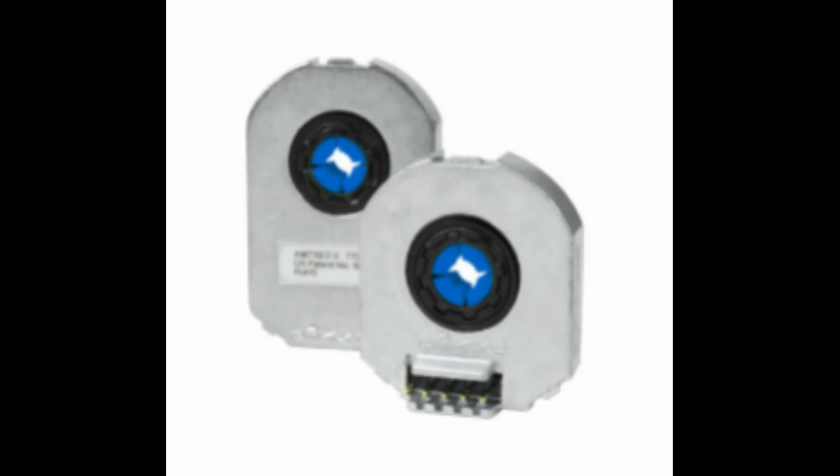Strengths of rotary encoders: highly accurate at measuring rotation, and easy to implement in a system. Weakness: it needs to be homed every time it's used, cannot hold position data when losing power, and is vulnerable to dust getting inside the mechanism, interfering with contacts and interrupting the signals.